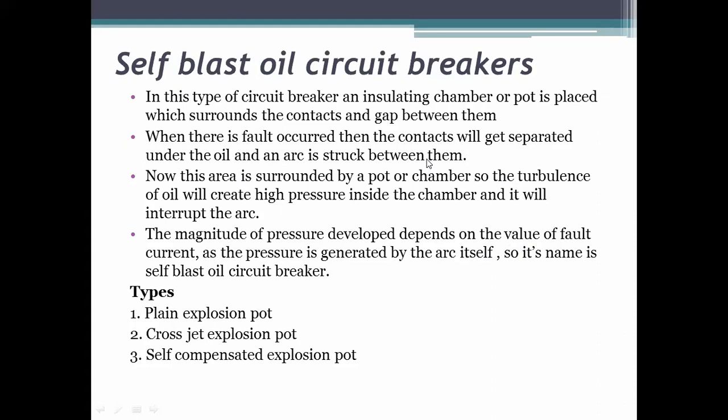So what will happen? When any fault occurs and you are moving that contact, the arc will be developed between them. Whatever arc is developed will be in that oil only, because that pot contains the oil. Now this area is surrounded by a pot or chamber, so the turbulence of oil will create high pressure inside the chamber.